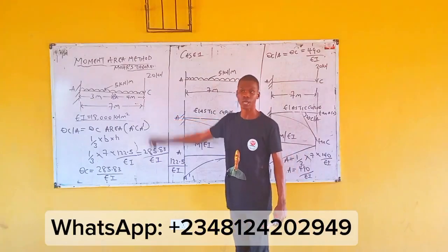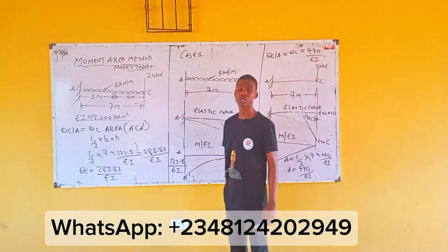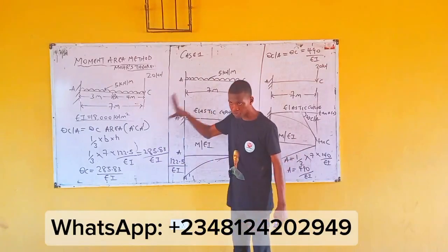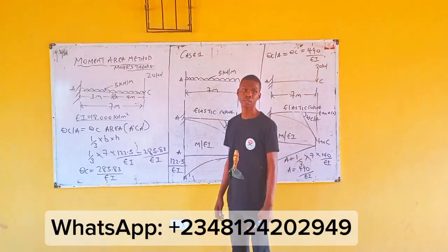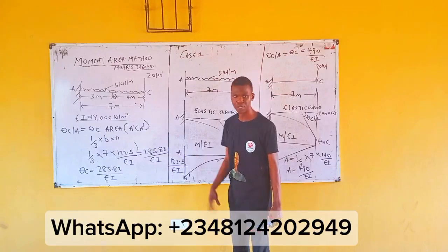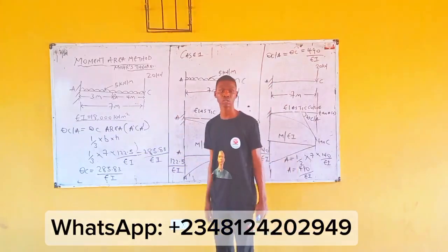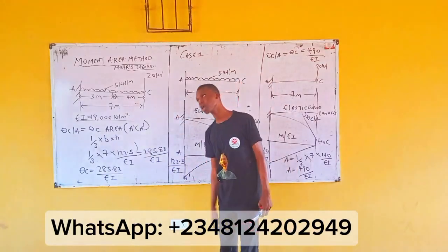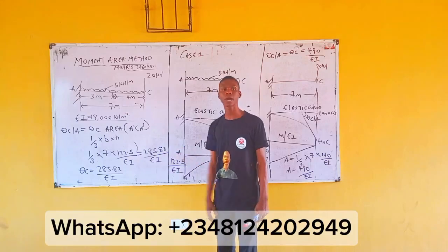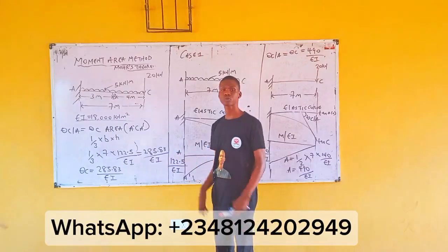Are you with me? Now you get the main question itself, the slope of the question itself. So if it's for a simply supported beam too, that's how it works. If it's for a simply supported beam, you separate, you split. You solve for UDL, you solve for point load. If it is two point loads, that's the same idea. But now, you solve the questions.